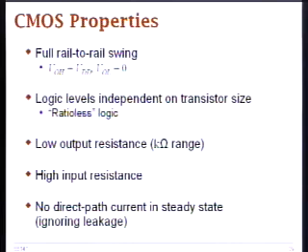But in DC condition, you will have your gate that's connected to the output of the previous gate, and the current to the gate is negligible in DC, almost zero. So you have very little loading and still clearly defined DC levels. And if you ignore leakage, there is no direct path current in steady state. You have either 0 or 1, and no current in steady state.